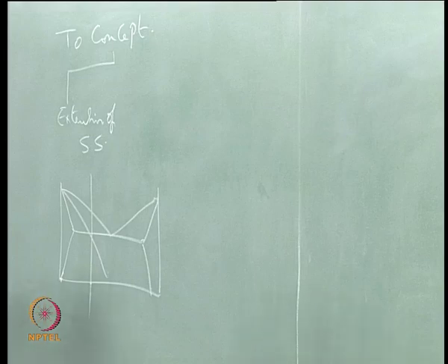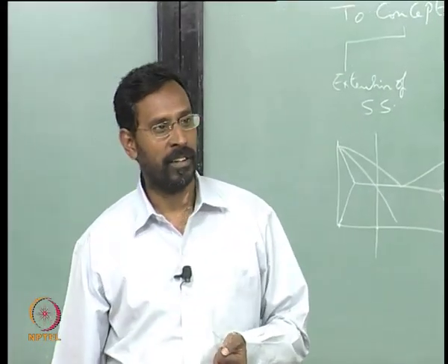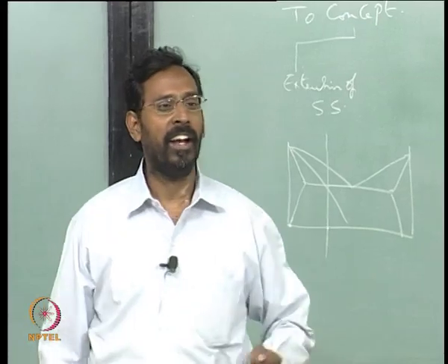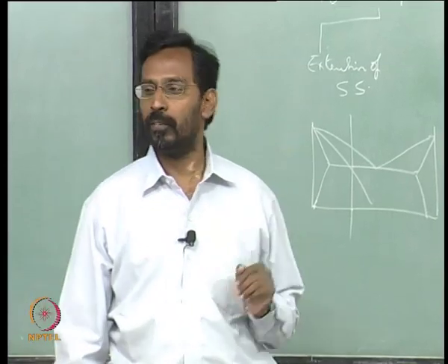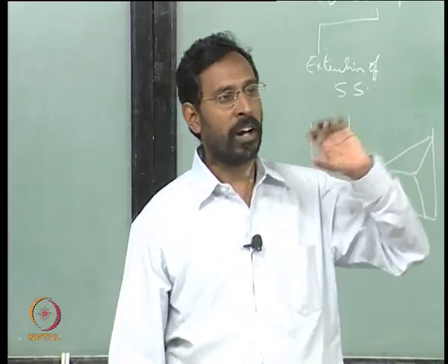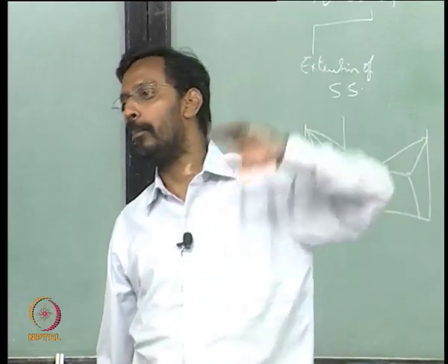So this is the most crucial aspect of the T naught concept, and that is what you get whenever you undercool. So undercooling can give you a variety of things. One thing that we have seen earlier in the beginning itself is that undercooling can lead to a higher nucleation rate and can give you finer grain sizes. So the fine grain size that we usually see at faster cooling rates is basically coming from higher undercooling. But yesterday, if you remember, we talked about this particular undercooling and higher nucleation rate, we are only concerned with the upper part of the C curve.